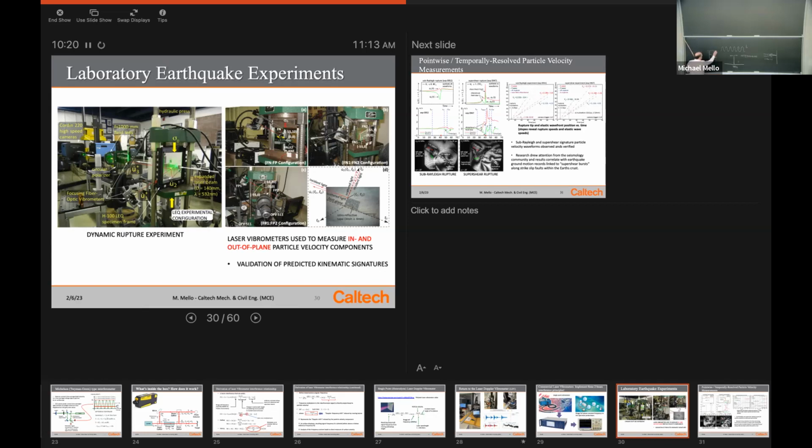So you prepare these two separately, and then you put them into the press, and you have the press by virtue of friction. By virtue of the friction along this interface, these two plates are kept from slipping. Can you imagine that? Okay. In other words, if there were smooth surfaces, as soon as you push on them, you would think, gee, they'll just slide, right? But if these surfaces were prepared beforehand and roughened appropriately, and this angle was kept within a certain range, you can get static friction to hold that plate against that plate, okay?